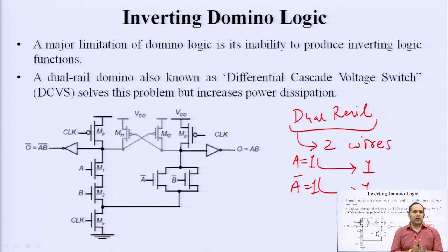Okay. A differential circuit is one which is also complementary in nature, so that one part of the circuit runs under certain conditions and another part of the circuit works when the conditions are complementary. Like NMOS and PMOS are complementary to each other, something like that we are using in a differential circuit. Okay. So, DCVS or differential cascode voltage switch you may have read before in some other sources. What it basically means is that it uses cross coupled PMOS circuits.